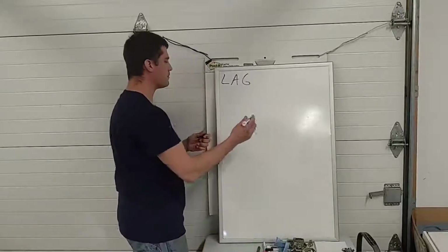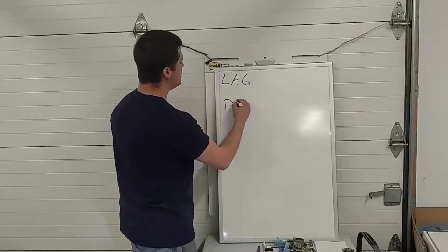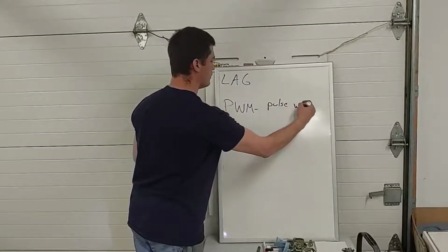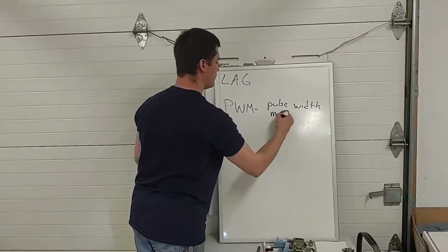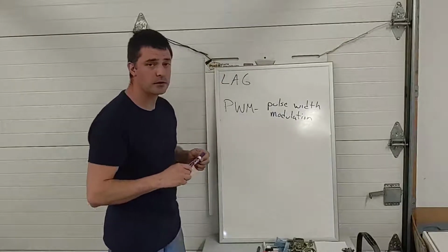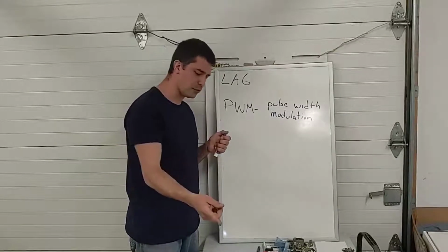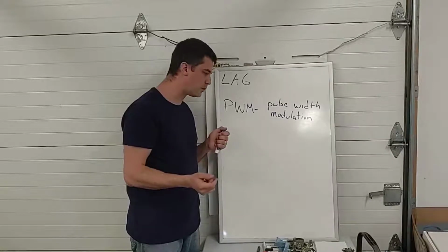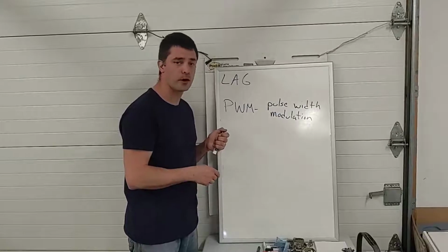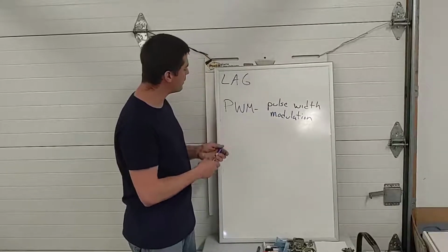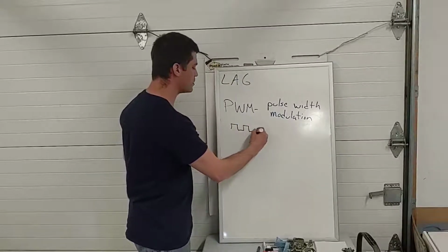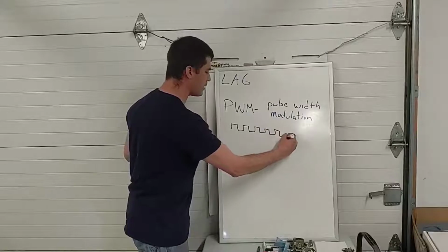And the last thing I should mention, something known as PWM, or pulse width modulation. We're going to discuss this in detail in another video, but I want to make clear that the computer is not sending 1 volt to this throttle to make it open a little bit, or 2 volts to the throttle to make it open a little bit more. You notice that at 2.9 volts even, that throttle opened wide open. The reason for that is the computer actually pulses or modulates pulses of voltage to that throttle, and I cannot duplicate that here on my bench.